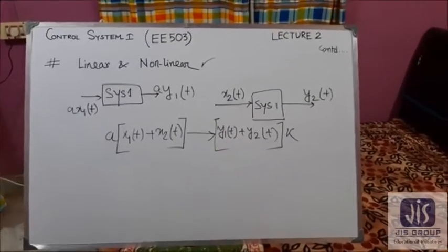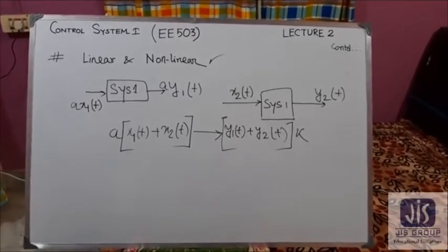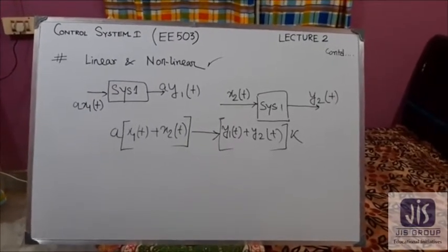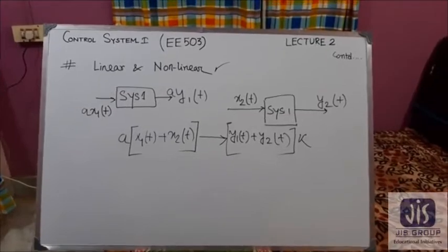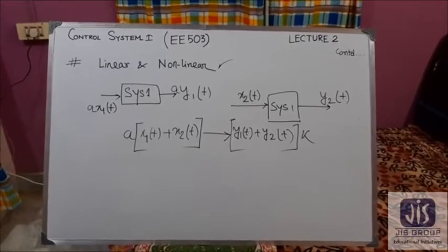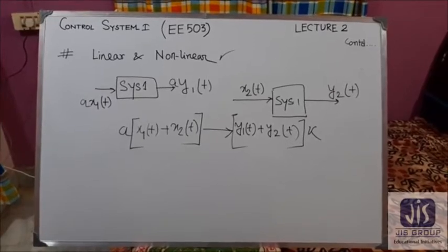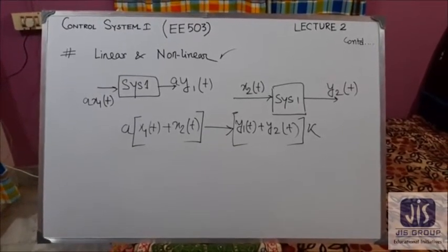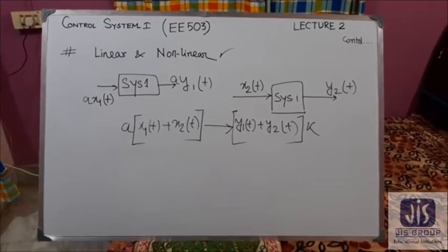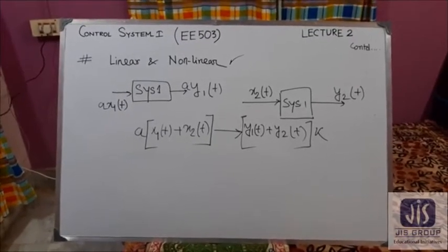Now, perfectly linear systems do not exist in practice, and non-linearities are caused by hysteresis, saturation effect, backlash, dead zone, etc. Non-linear systems are usually difficult to treat mathematically, and there are no general methods for solving them. However, if the deviation from linearity is small and considered insignificant for the problem, then in such cases the non-linear system can be approximately linearized about the operating point.